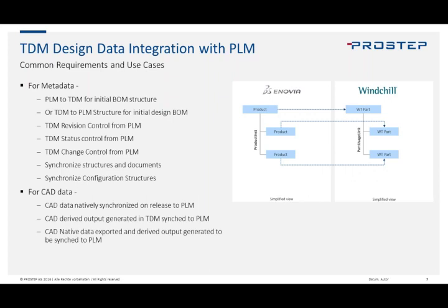But you might not have something like a Windchill derived output that you might need, like a Creo View. So in order to accomplish that, you would export that CAD data, CATIA data from VPM, generate a Creo View outside, and then put it into Windchill. And that fulfills the functionality you need in Windchill in order to have that visualization there. When you're using the system, it'll have a proper representation.